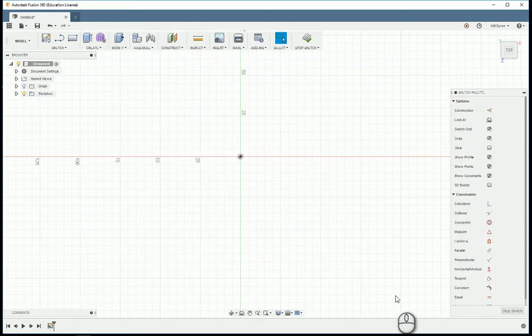One other thing to be aware of, whenever you start to sketch, you'll see a sketch palette. The sketch palette is how you can align shapes as well as set physical constraints on how it's made in your grid or in your viewport. Whenever you want to use, for instance, 2 circles, you want them to be equidistant all the way around, no matter what. That's when you can start putting physical constraints.